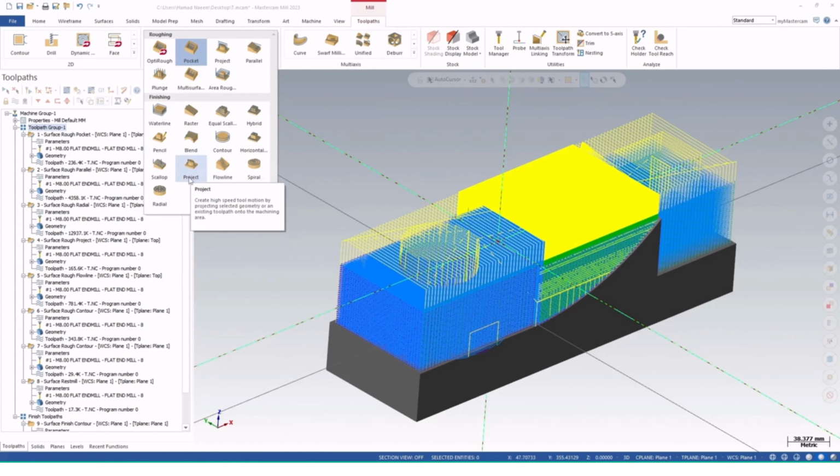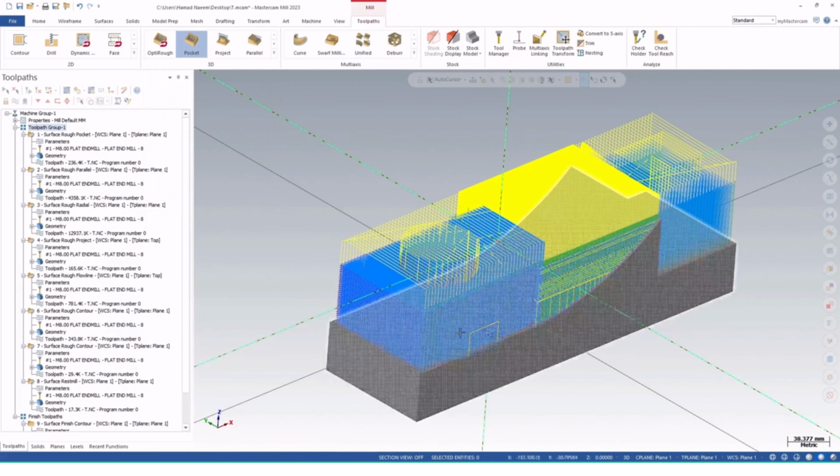First you have to perform all the roughing operations, and after that you have to perform the finishing operation to make the surface shine more, look closer to your design and closer to your sizes, and make the surface more accurate. So I hope you understand.